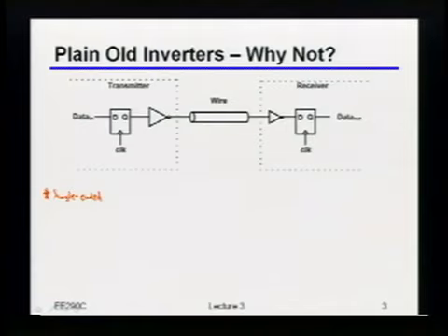Okay, when you say noise immunity, what do you mean? If you have any coupling from nearby signals, you won't be able to reject any common mode. Okay, that's right. What you mean by that is basically there's no common mode rejection. That's certainly true just because it's single-ended. And of course, let's even look at the circuit itself. What's bad about this particular circuit as, for example, being a receiver? Why don't you just throw inverters on there and say, that's my receiver?